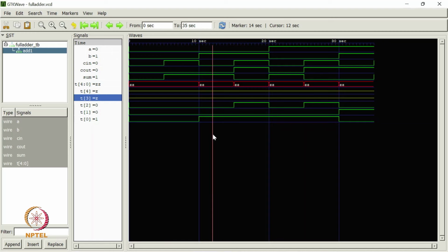So, Verilog is different from normal programming languages in this way itself. In normal programming languages, we consider the state as either 0 or 1 if it is a binary state. However, in Verilog, a state can be a 0, which is binary 0, a binary 1, or it can even be a high impedance state, which is actually possible in electrical circuits. If we talk about, let us say, the output of a certain gate, at some point it may be possible that the pull up network is off and the pull down network is also off.